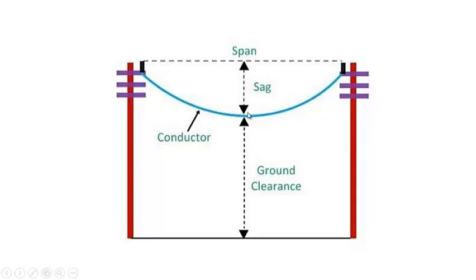You'll see these two forces will be independent of each other. They will not cancel each other. There will not be any equilibrium in that case. So that is why it will always form such type of a catenary or such type of a curve, so that the tension, which is slightly inclined to the horizontal, will have its horizontal component and vertical component. The vertical component will balance the weight, and this horizontal component will balance the horizontal component on this side. So when it sags a little bit from the horizontal position, it will definitely be in equilibrium because all the forces will then cancel out.